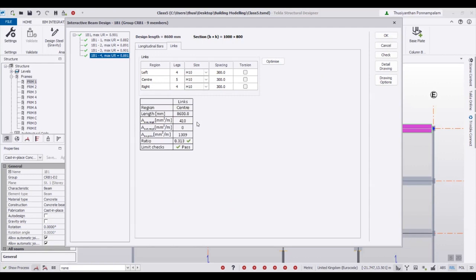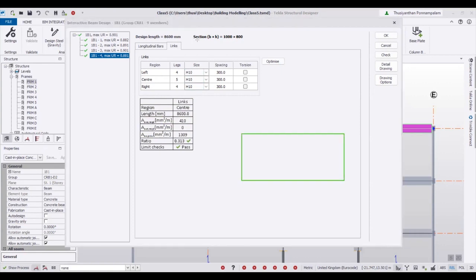Okay, so you can see this value. See here, this one is showing 4410, but I am overproviding. You may ask why overproviding. Because I am following the basic detailing rules. Because this beam is 1 meter wide, so that's why I provide minimum 4 legs.